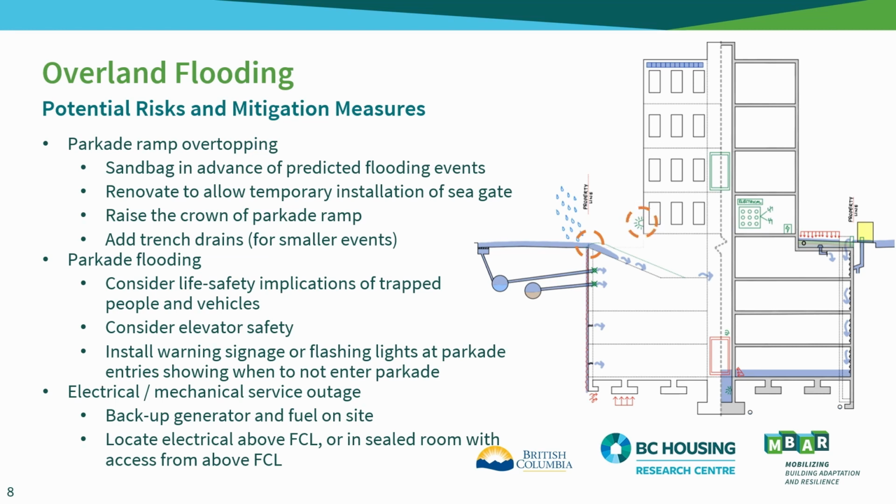Before a flood event, consider flooding in the parkade and the potential for individuals and vehicles to become trapped. Additionally, consider elevator safety, as flooded floor levels may allow for water to enter the elevator. Consider what safety protocols for trapped individuals in the elevator are being implemented. Having a backup generator and fuel on site can help relieve an electrical or mechanical service outage, which results from a flood event.